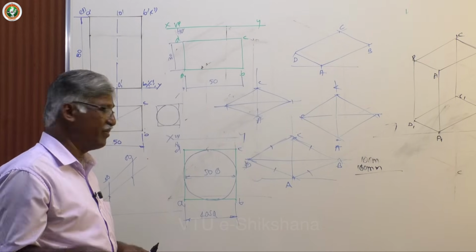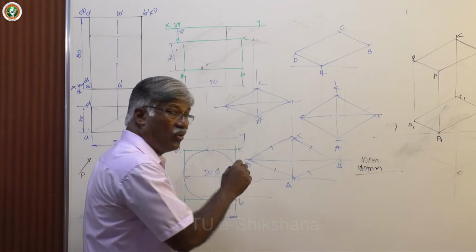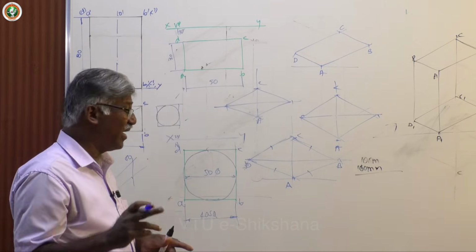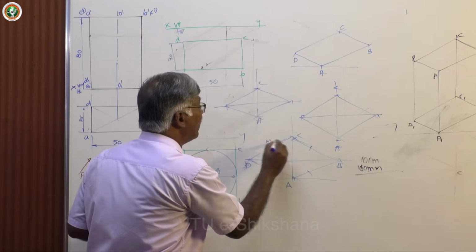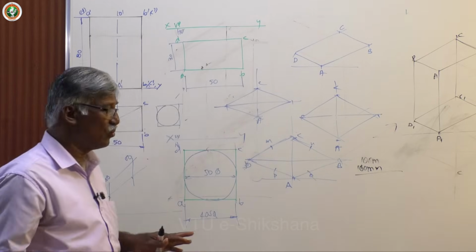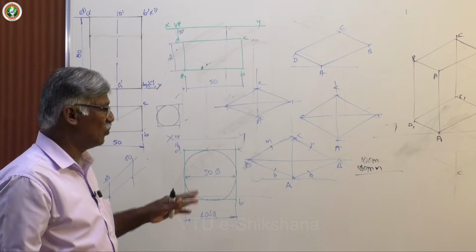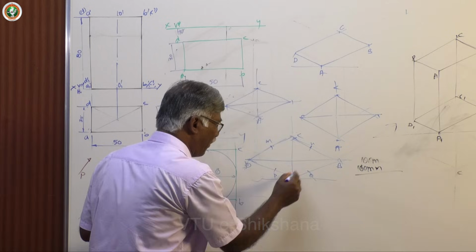This is called the 4 centers method. How to get those 4 centers and radii, what are the radii to do it? It's very easy to understand. Let me name these points M, N, P, Q, for explanation purposes; you need not do anything, just identify those points and then proceed. Now, join the midpoints of the sides with the opposite corner.